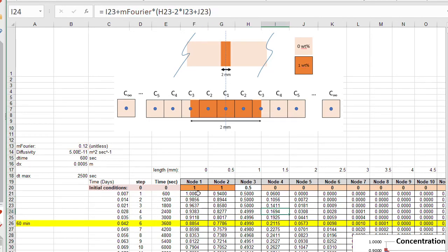All right, and so that really is all there is to this problem, is fixing that equation here. So again, we know it's not a surface because of our sketch. This tells us everything. It's an internal node. It also tells me that when I want to look to the left, that's C2, which is right here to the right. And so I just change it. And that's it. Then I just go ahead and put in my initial conditions and just run this.